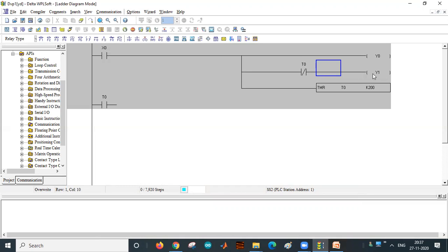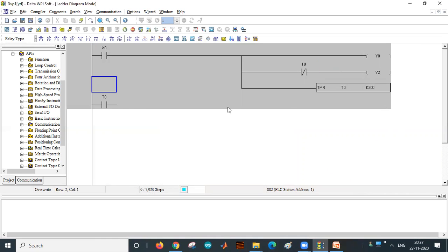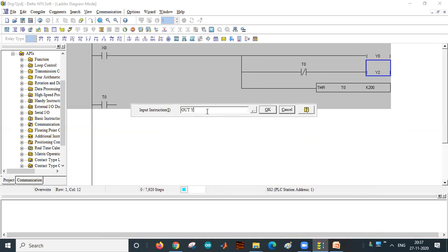What is Y1? Y1 is connected with the star contactor coil. So you have to de-energize the star contactor coil so that the star contactor will open. Along with that, you have to close the delta contactor, which is Y2. Sorry, the delta contactor is Y2 only.